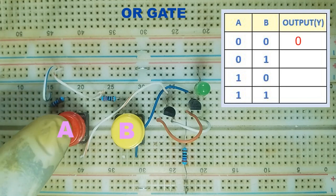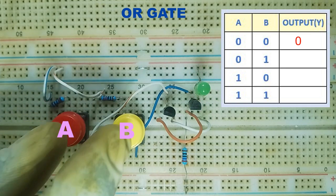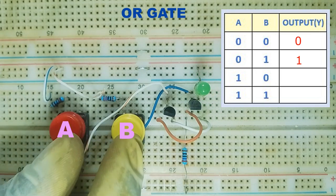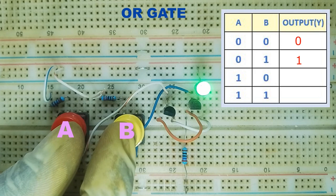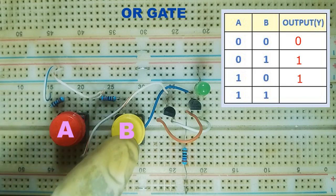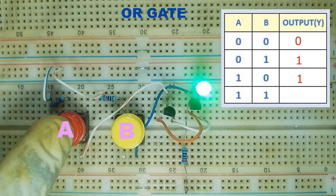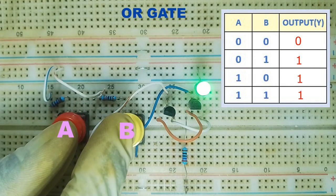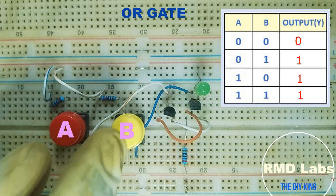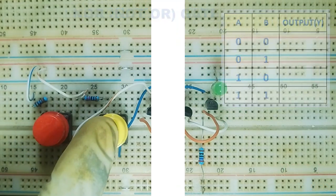Well, here is the completed circuit. Let's test it by driving its inputs A and B high and low to check its functionality. Currently, both inputs A and B are at logic 0. And as you can see, the LED at the output is off, indicating we have a 0 at the output. If we press the input A button, the LED comes on, indicating a logic 1. Doing the same for input B also turns on the LED. Let's now press both A and B buttons and see the result. As expected, the output remains high, and the truth table of an OR gate is generated.